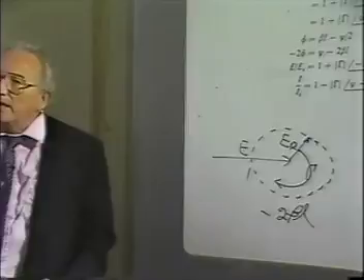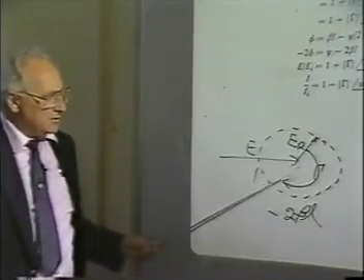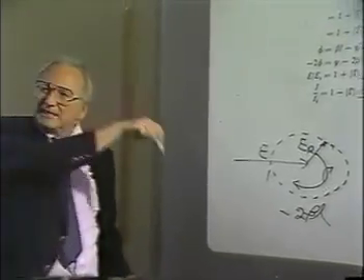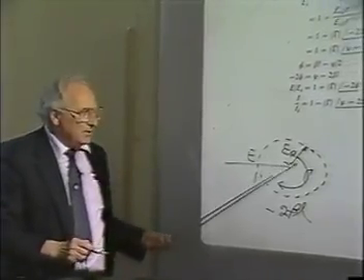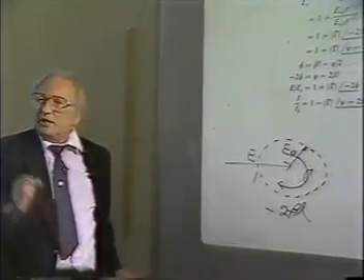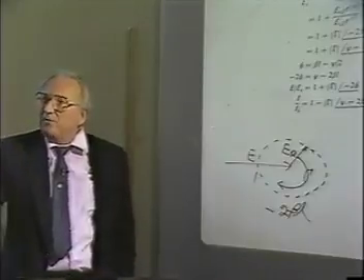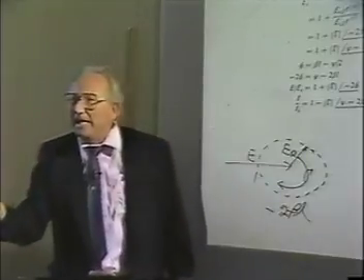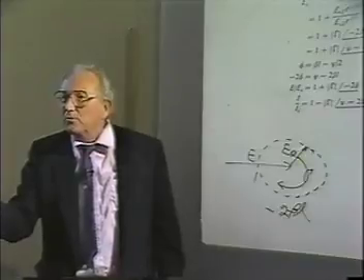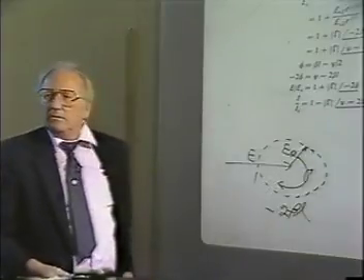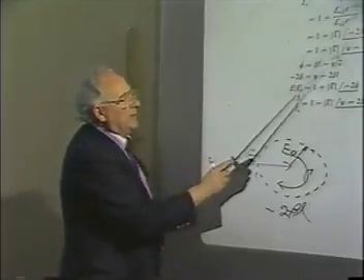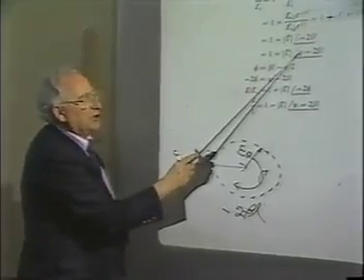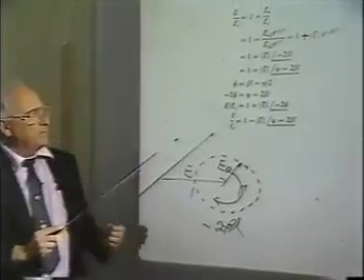Minus 2 beta L. It means that every time this travels 20 degrees on here, it represents 10 degrees on the transmission line. If this travels 90 degrees on this chart, it means that it's traveled 2 beta L of 90, which on the transmission line is only beta L. We showed that on the previous diagram. That's what's rotating, gamma. This value here, I'll show you what this means on the next chart.